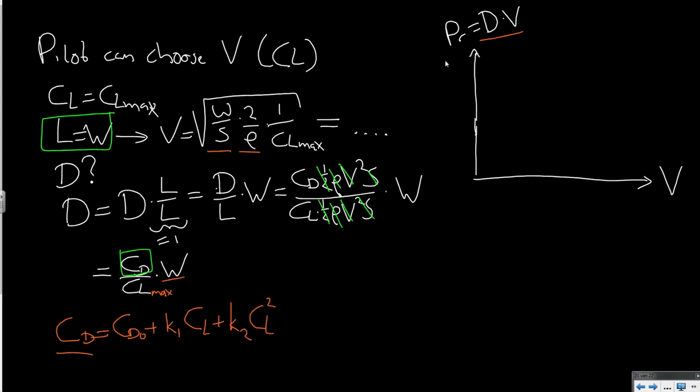And since we already took a specific value for CL, we can actually calculate the value of CD and write it out. Now we've determined CD, we have determined CL. If we know the aircraft weight, we can calculate drag.